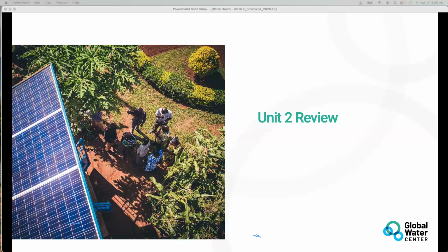Technically speaking, I would say 7 meter cube per hour is maybe the maximum yield of the borehole we are referring to, and 4 meter cube per hour may be the starting target flow rate when they conducted the pump test at that time.